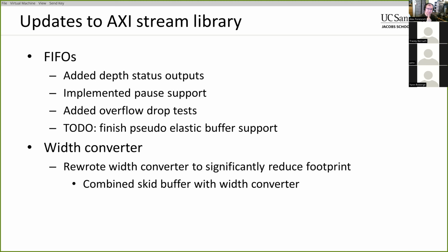I didn't pull those up, but on a design where we have multiple ports on the same interface, it saves a pretty large number of logic resources. And I guess on all the 25 gig designs, there's also a 64 to 128 bit conversion that takes place using the width converters. So this will make that a bit smaller. So it's definitely going to be useful to have this change made on the switch, because that could potentially have a lot of ports that need to be converted between different widths.